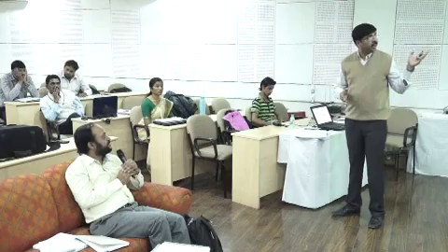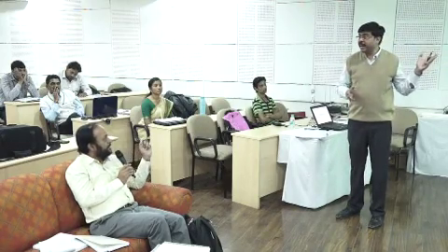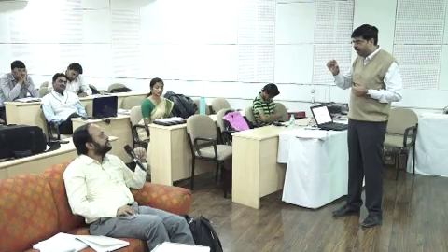Sir, I have taken a total of around 3,800 cases. I'm asking, there is no point in taking so many cases, only those cases where these levels are too close to each other. Right, sir. Like you are saying, the peak of the inrush depends on the instance of switching. If the instance of switching is near 90 degrees, the peak is very small. Those cases also I have incorporated in my study.